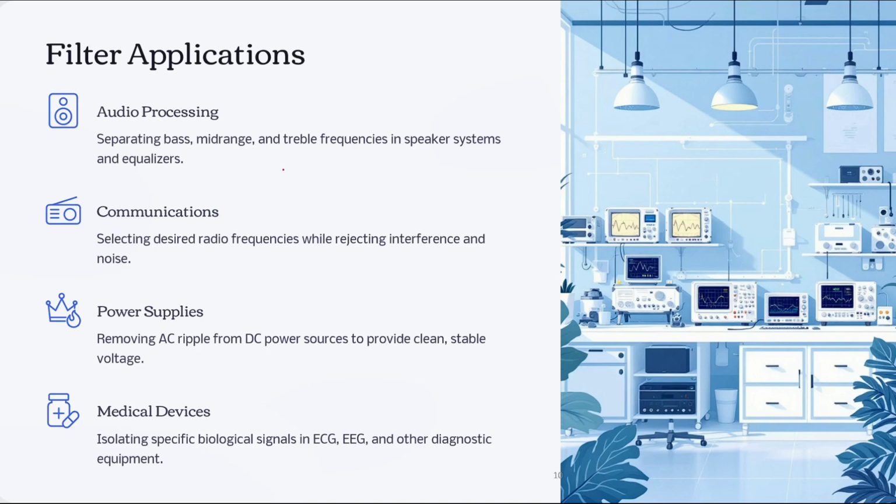So let us consider a quick exercise. Let us consider a low pass filter with a resistance value of 1 kilo ohm and a capacitor value of 100 nanofarad. To determine the cutoff frequency, as we know, it is given by 1 by RC. Putting in the values, we obtain the cutoff frequency to be 1.59 kilohertz, right? So this low pass filter will pass the audio bass and block the higher treble above this range, that means 1.6 kilohertz.